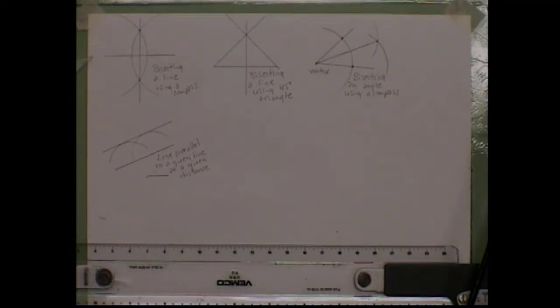So you can do something very similar called a scribing method, where you can outline the radius of your hot tub and mark it on your board. You just have to have a certain instrument, kind of looks like a compass, but you just roll it along the outside of your feature, your surface, and it marks it with a pencil on the other end on your wood where you need to cut that. It's called a scribe, but it's the very same kind of concept because you're using the same radius.